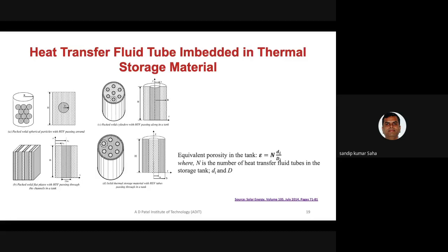So what people adopt is that they shrink the diameter in those cases and try to model the contact point. They try to show that if I shrink the diameter by say 99% or 98%, then how much change in the result will happen. So this is the first technique in any numerical model of this type of storage system. This is the discrete element method. I am not showing it here, but the formulation I will show here is equally applicable there.